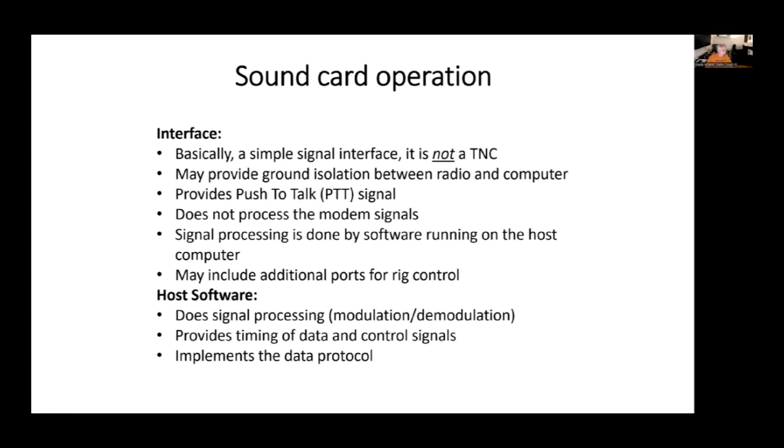It's not a TNC. It doesn't do the same functions as a TNC that the sound card and the computer together do, but the sound card itself does not. It may provide ground isolation between the radio and computer. It certainly can provide a push-to-talk signal. Doesn't always have to, but it can. It does not process the modem signal.